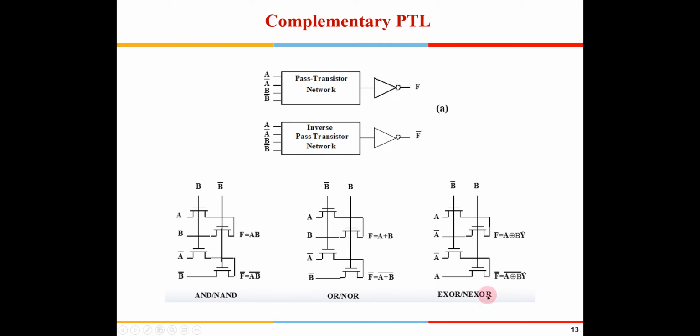Same thing for any gate function, right? If you have to implement it, you can do that. And the principle of design is like this. You take one of the inputs as a variable, put two gates for 0 and 1, and put that value in the function. Whatever you get, you just keep putting here, right? So I have put B here, but 0 also would work fine. Similarly, if you say A or B, if I put B is equal to 0, what?